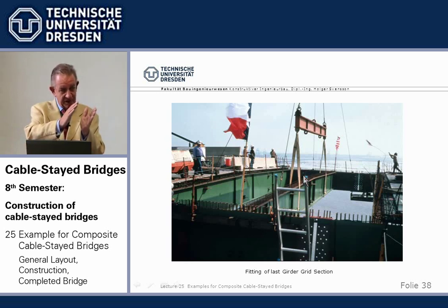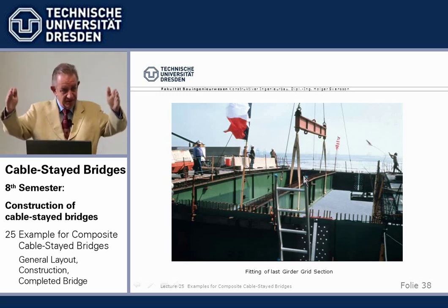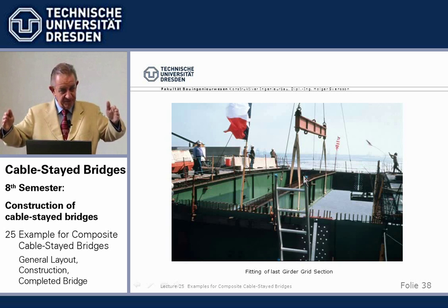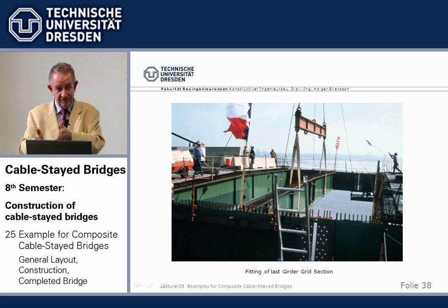The bearings were a little skew, and the hold down piers were flexible enough also to the outside, everything to the outside. Then we have enough space getting in the last piece and then taking back the jack at the corbels, at the towers, fits in, cover plates, high strength bolt, done.